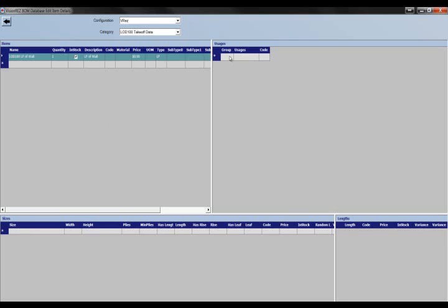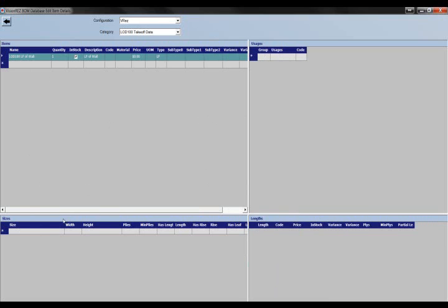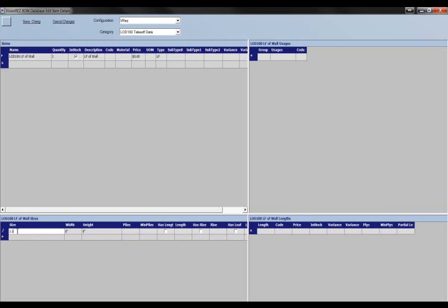Now the usages aren't really important with wall data. That would be more for structural members, beams, that type of thing. So we'll just skip that cell. Down in the bottom left cell, we're going to do sizes. We want to do 3.5 by 8 foot 1 1/8 as a size. The width, I happen to know that the width of those walls, including sheetrock and everything, is 4.5, so I'm going to put 4.5 for that. The height is 8 foot 1 1/8.